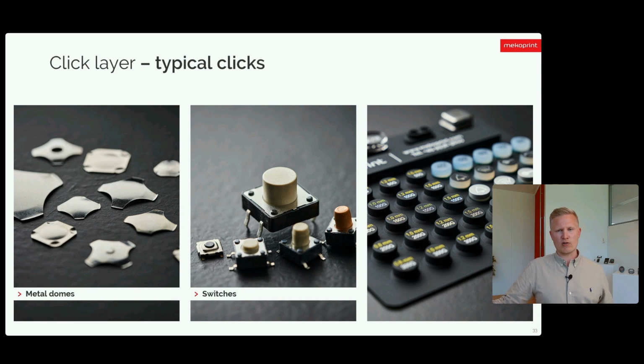Tactile switches can also be used to create a click, but the selection is a bit smaller. Tactile switches are normally used when you have a PCB with soldered components, where the tactile switch is also soldered onto the PCB in the same process. Or if you have very limited space on the circuit layer, a small tactile switch will give a better click than a very small metal dome.